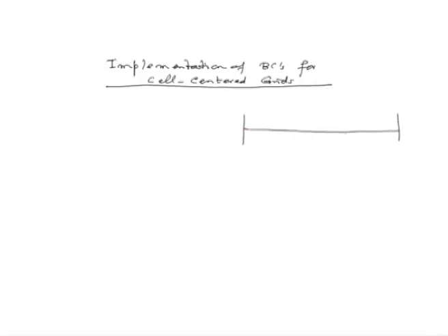This is what will happen. We will first divide our problem domain into control volumes, and their centroids now become our computational nodes. This is our cell centered grid. Now, if boundary conditions are specified at the ends of the domain, how do we account for these? There is no computational node, there is no control volume exclusively linked to the points on the boundary.